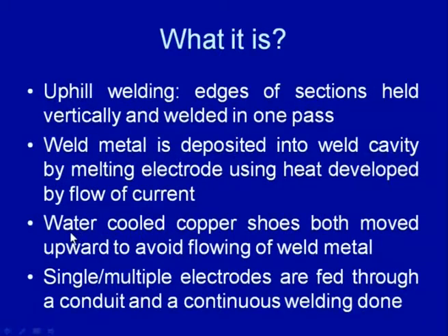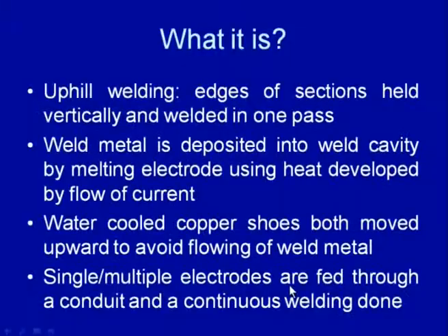Further, in this process, water cooled copper shoes are used on both sides of the weld region which is being made, to avoid the flowing out of the weld metal, and this process can be a single or multi electrode process through which current is passed and the heat is generated continuously for developing the weld joint between very thick plates.